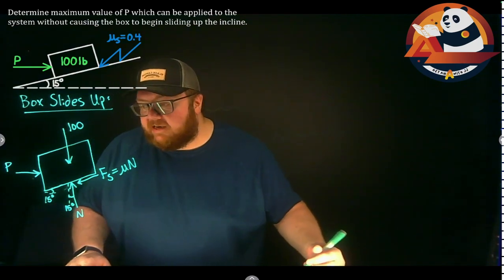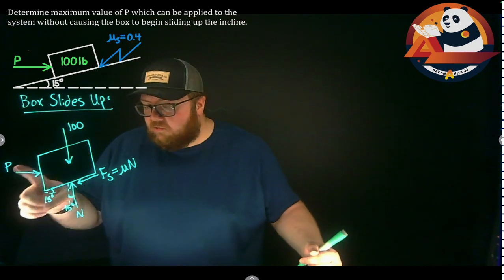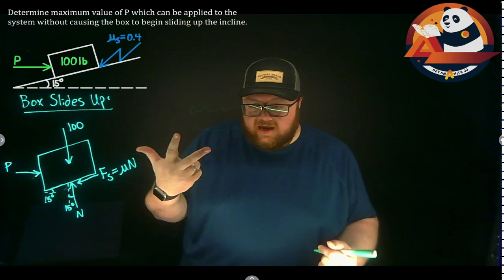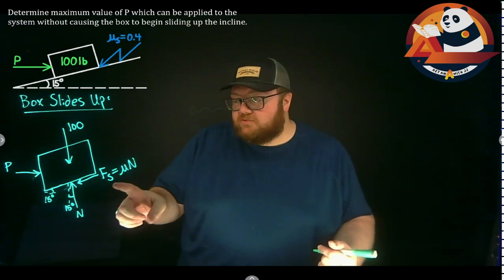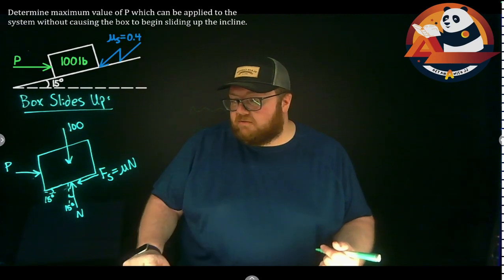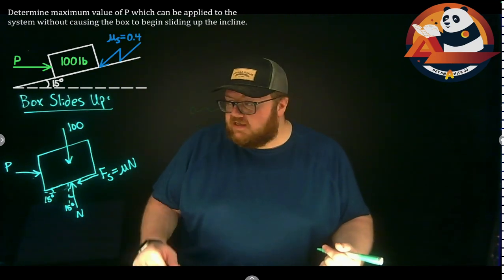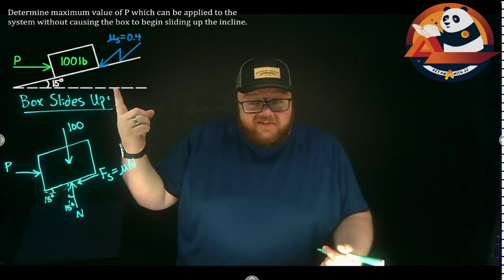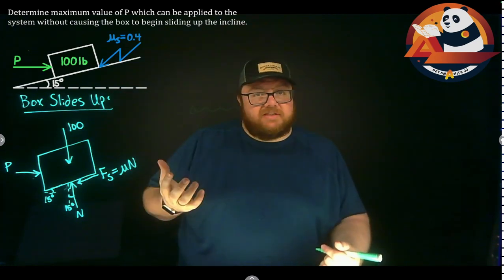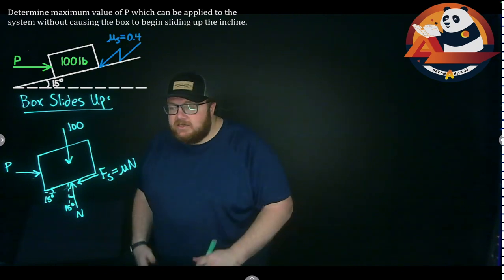It's kind of how we're going to go in and tackle this. What are we going to set up in here? I have 1, 2, 3 unknowns in here: P, N, Fs. That means I need 3 equations. One of them I've really written out here. This is one of my 3 equations. Fs is mu times the normal force. We know it's at 15 degrees. So that's one equation, and then it's just equilibrium. I can sum forces in the x for a second one. I can sum forces in the y for my third equation. So let's just set those up.